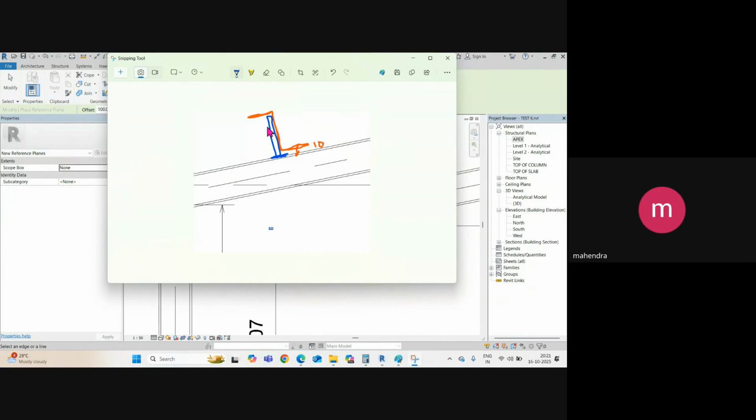Then on the side they just add the bolts here, with the same criteria: 35 from this edge, 35, then 17, then 35, and then add the purlins. If you design the proper size of purlins, you can get the exact values. This is how this type of connection works.